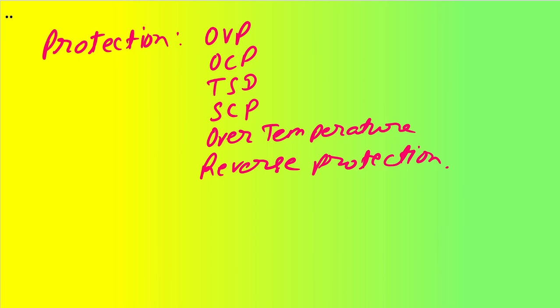Next parameter for the regulator is what are the different capabilities that the regulator is carrying out. So whether it is having over voltage protection, it means if my input increases more than the range, whether it can protect itself, or it will shut down and protect itself. Similarly, over current protection. So let's say the output got short circuited, so a lot of inrush current will be drawn. So at that time it should be able to save itself. So these are the protection mechanisms that should be available with the regulator if it is needed for your design.